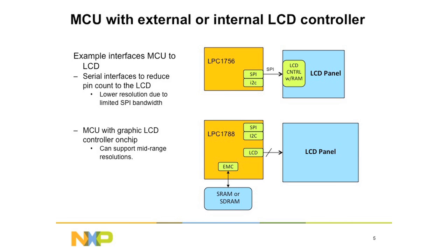Right. Okay. So a couple ways you can do this, depending on the LCD you're interested in. We do have customers that are using, in the Cortex space, no embedded controller, but an LCD panel that actually has the controller built in. That might be simple and from a lower resolution point of view, but you're gonna lack a few things in terms of bandwidth. You're not gonna get the 15 frames per second or some of the color resolution that you would get if you had the LCD controller built into the part.